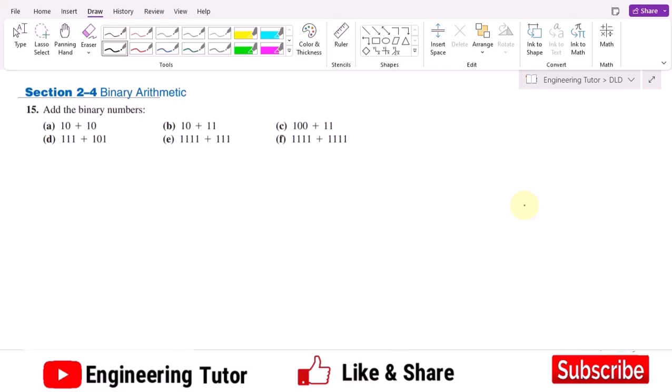Before doing the addition in today's lecture, we are here to see some basic operations or fundamental additions which will be useful throughout this lecture. In order to add any bits, first we have to see that 0 plus 1 is always equal to 1 plus 0, and that is equal to 1. Similarly, 1 plus 1 in decimal is 2. So in binary this will be 1 0, because 1 0 in binary is equivalent to 2.